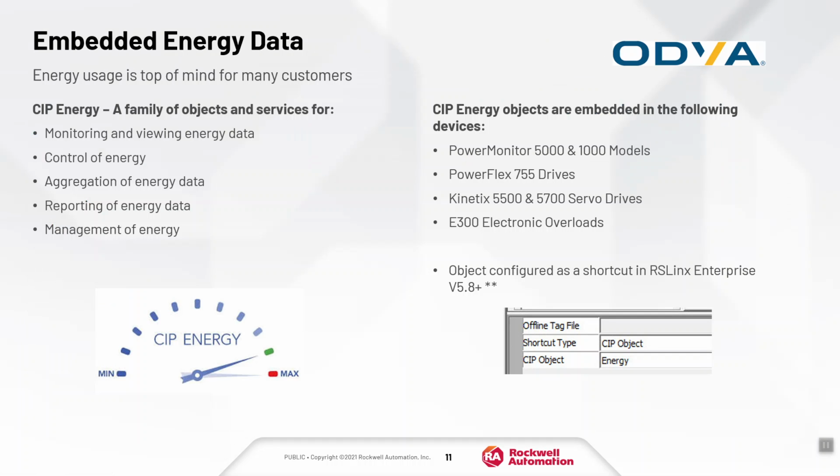Once you do that and that SIP energy object is subscribed to, we can then push data to a FactoryTalk View system. You could push that data and use that data or historize that data in a way that is useful to you. So think of this as a really simple means to capture energy-related data directly from end devices.